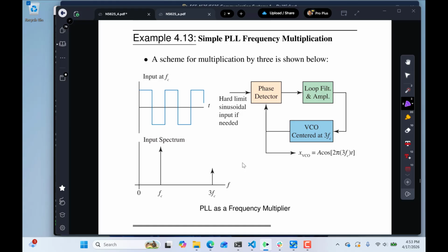There's some other tricks you can pull with a phase lock loop that are not particularly exotic or anything. It's just building on the same idea that a basic first order loop, if you feed it an input frequency, a clean signal that's not a received noisy signal, we can make the VCO lock to that signal very easily with the loop amplifier and a proper phase detector.